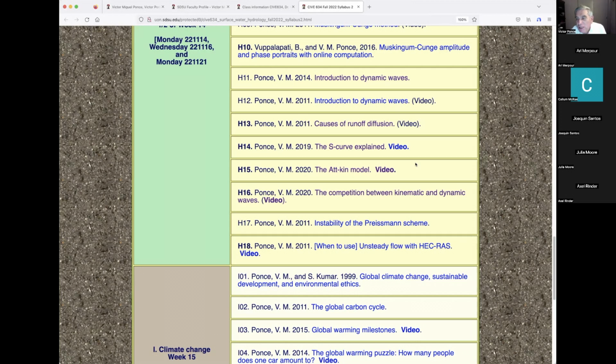Over the 80s, middle 80s, you wouldn't see DWOPR. By the 90s, DWOPR was gone. Dam break was successful through the late 80s and early 90s and so forth. But then in the year 1998, I believe it was 1998 or 2000, the Army Corps of Engineers came up with HEC-RAS with dam break. They did a dam break inside, not the dam break of the National Weather Service, some other dam break. And since the Army Corps has more wherewithal than the National Weather Service, they took over. So now if you want to do a dam break model, you go to HEC-RAS and you do it with the Army Corps model.